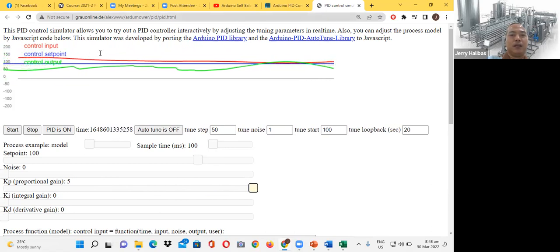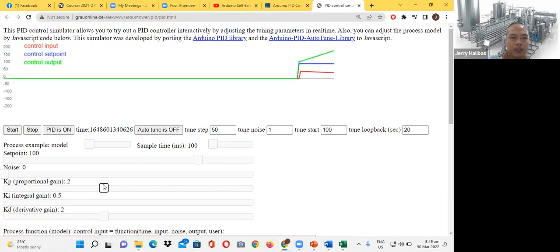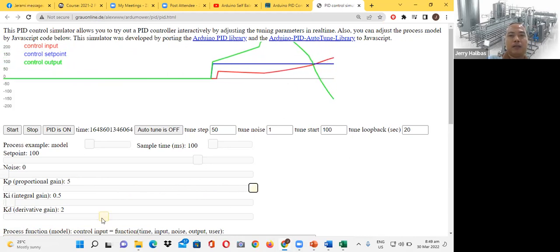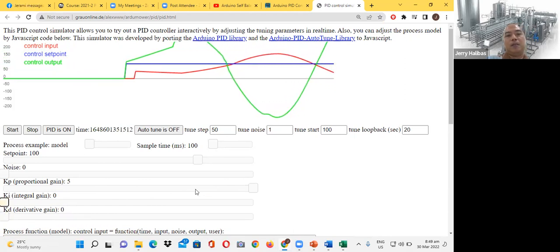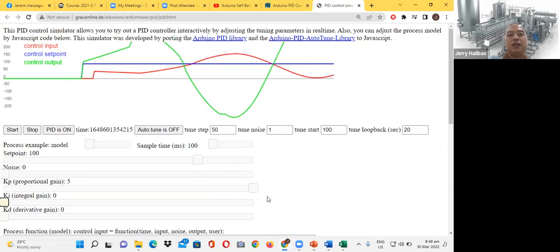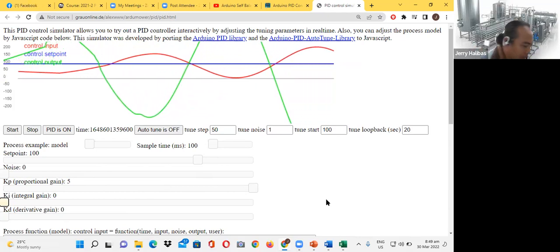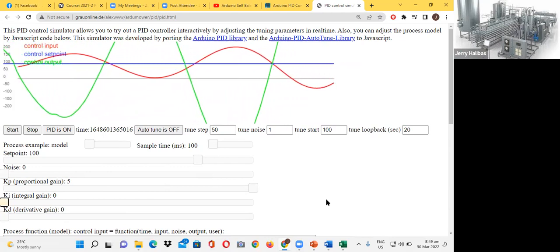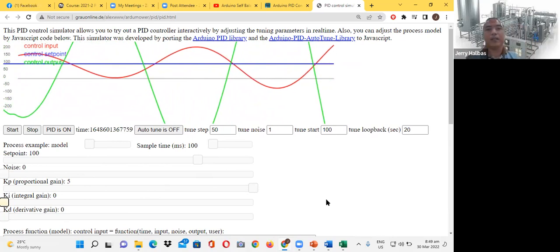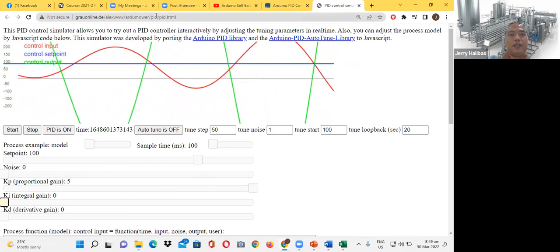Let's reset this. Set. Then increase the proportional gain straight. So you can see it goes higher. I removed the differential and integral. So it becomes stable? This is the proportional: it keeps swinging up and down. It oscillates up and down. Okay? So, let's reset.